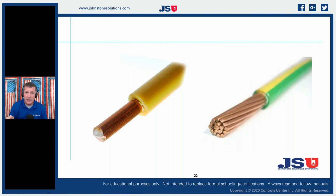Our ground wire was an emergency path. Well, now in communicating, that ground wire is actually essential for communication. So if I have a ground wire that is heavily oxidized and corroded, I'm now interfering with my communicating capabilities of my entire system. So super important to understand grounds.